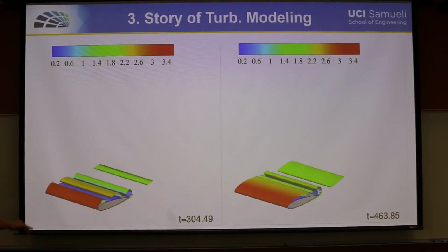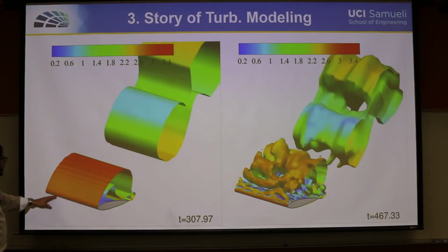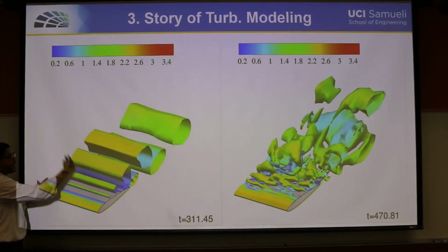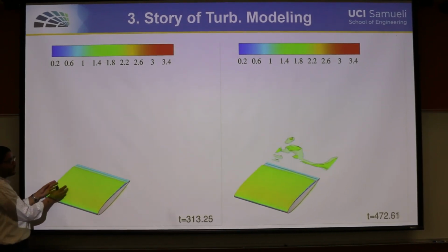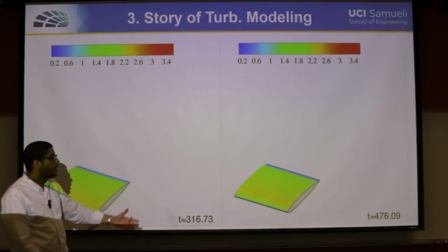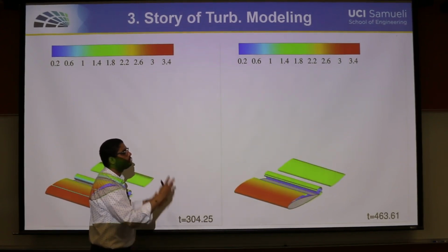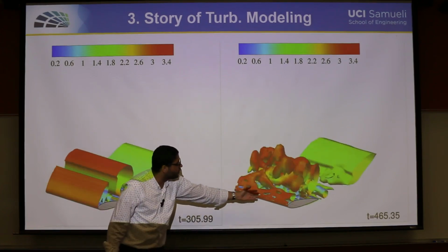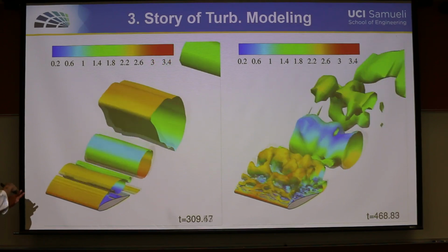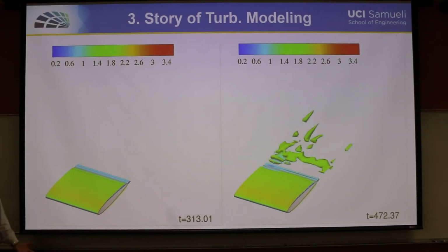This is the same CFD simulation, but these are 3D iso contours. As you can see here, even if that is a 3D simulation, you're not getting more than the edge of the vortex being extruded in the 3D domain. However, because we are utilizing the large eddy simulation here, we get those fancy iso contours of turbulence mixing, especially when massive separation starts to occur. You cannot get any of these solutions using a RANS solution. Okay.